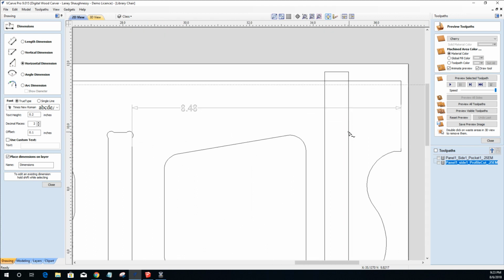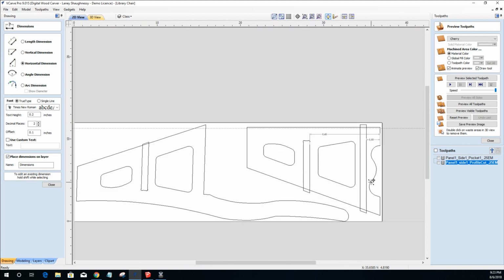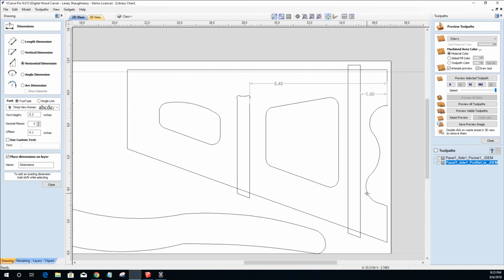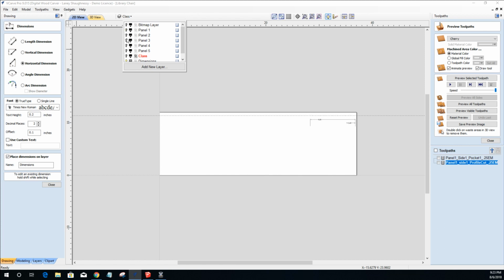The measurement from the spline to the lower part, that rectangle, is roughly 1.5 inches or 1.6. If you're drawing this, I'd be a little bit specific with that one. I want good meat in between the lower part of that spline and whatever curve or design I have down here. I don't want it to be real thin and fragile there. The whole purpose of the spline is to reinforce this whole area. Last thing I want is a weak spot here, so we want to be at least that distance away.